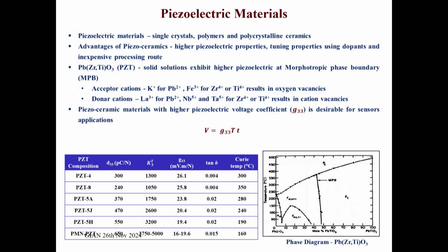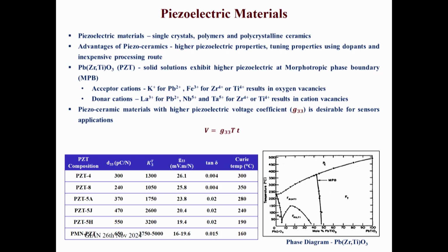And this is the Curie temperature. Up to that particular temperature, the material is ferroelectric. Above that temperature, the material is transformed to paraelectric. As far as barium titanate is concerned, the ferroelectric transition temperature is 120 degrees, and therefore, if you heat barium titanate kinds of substances up to or above 120 degrees centigrade, their ferroelectric properties are lost. So, this is the transition temperature, whereas in the case of lead based materials, the transition temperature is significantly high as compared to barium titanate.